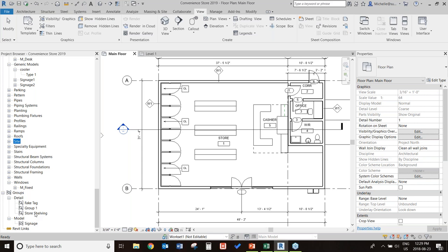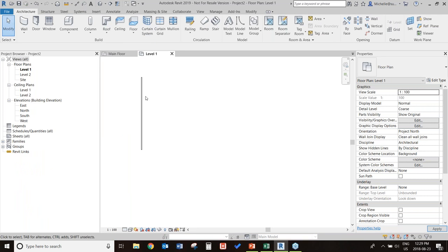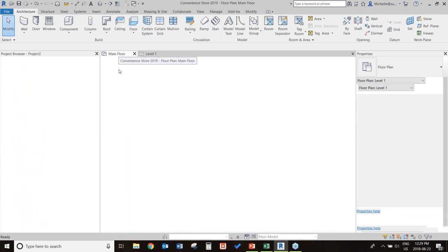So if you have a really good naming convention, you could even put a naming convention in place if people aren't supposed to use model groups as families, but if you can't get people off that train, maybe put a prefix in there, F splash pad, so that all of those get grouped together, and then people with the ability to create those families can take a look at those groups and make the ones that are required. So again, you'll narrow down which ones have been created as families and then copy and paste them back into this file over here so that you can see if that's something that's going to be reused.